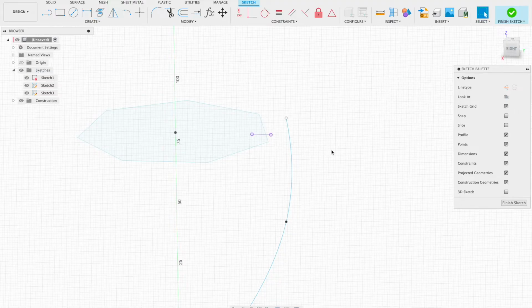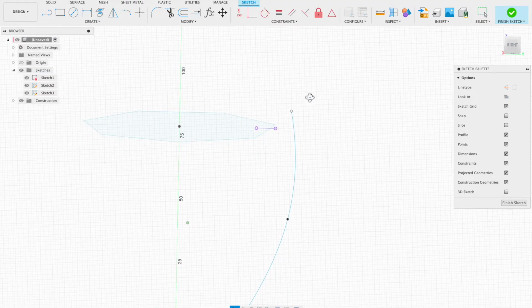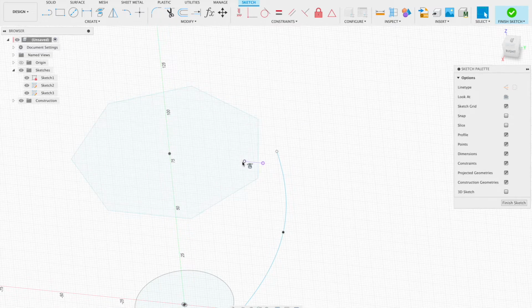So if I select OK, Fusion's telling me that this line would be this long when it's projected onto the current sketch plane. But I can't use this line because it's not giving me a point on the profile that I need for this spline entity to touch the profile. It's giving me 2 points, but those are not on the line, so I delete that.